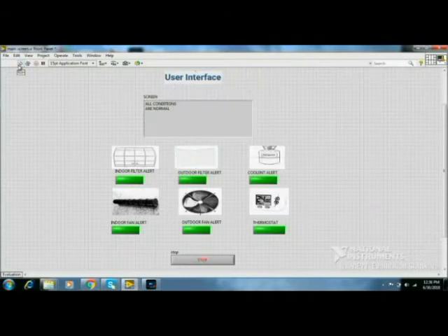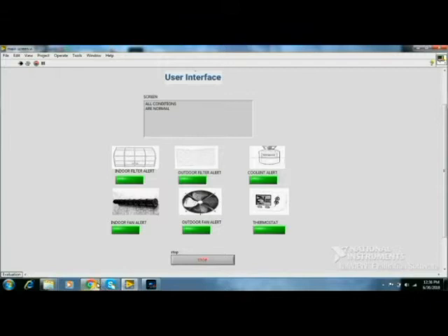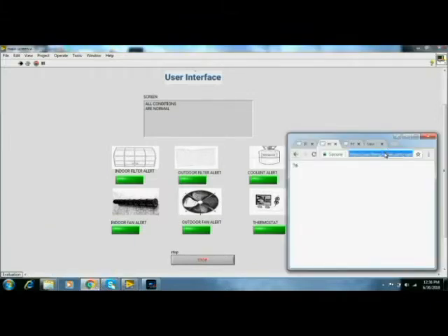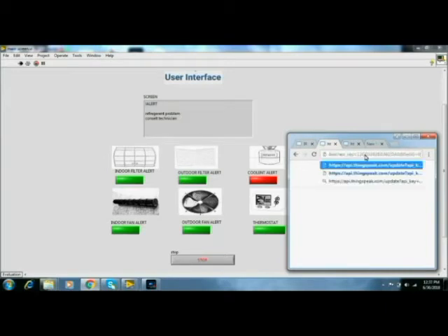So now we are running this program. I'm going to change the temperature of the suction line to 66 degrees Fahrenheit. As the temperature field is updated, an alert message should be printed. Coolant alert is printed, and it will take a little bit of time to display the message. Let's wait. An alert message is also printed here. Now we will change this back to normal. The alert LED is turned off.